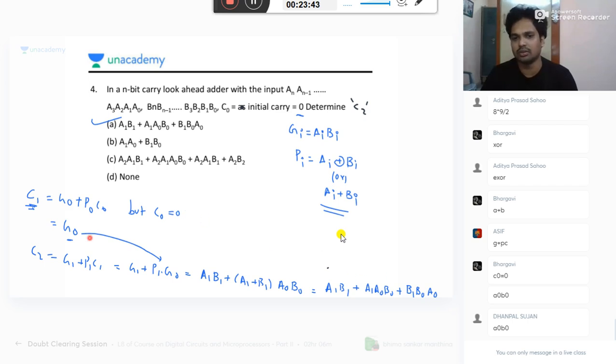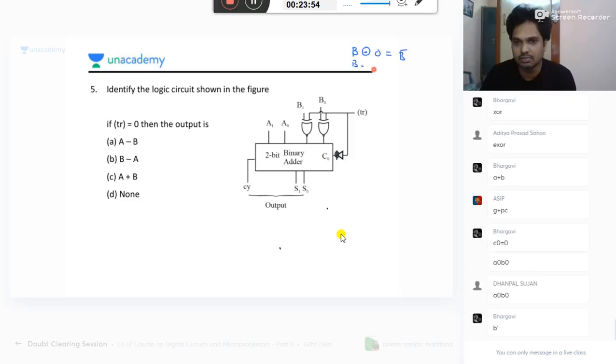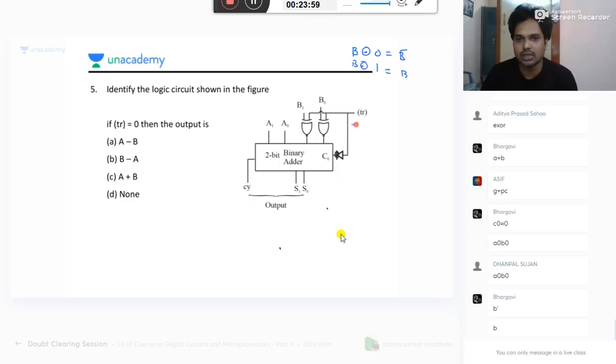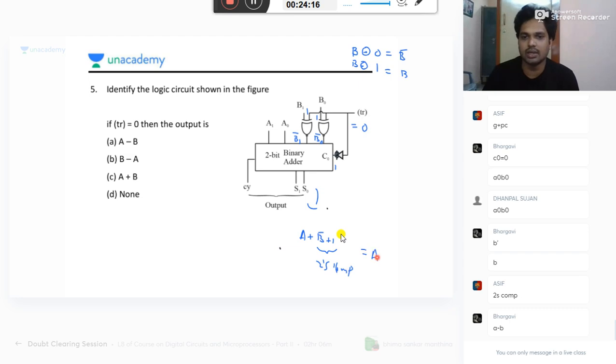Okay, you understand here. Vi greater than 2 equal to 1, else 0. What about here? Vi less than or equal to minus 1 will give you 1, else 0. Because it is connected to the negative terminal, here it is connected to positive. Always positive greater than negative, then you get 1. Otherwise, you will get 0.